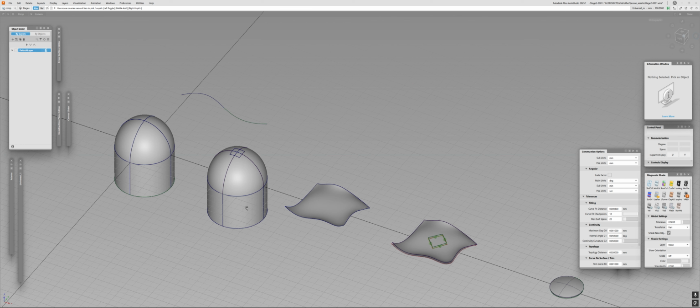Everything will work. But if the project is complex, if the surfaces are complex, there are a lot of surfaces, they join together at different angles with different domains, a lot of trims, the chances that SolidWorks or, I don't know, CATIA, whatever, can really make the proper thickening for your model are quite slim. So they will try to do it, and in most cases they will fail. And when a solid body modeling tool fails, it will return, well, nothing. It will not give you a thickness with failure. No, it just didn't do a thickness.